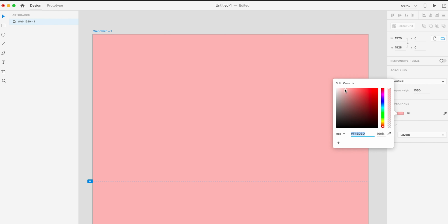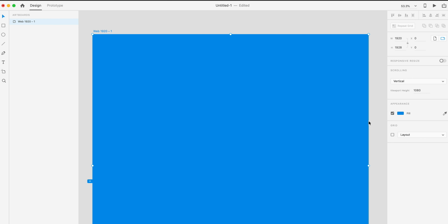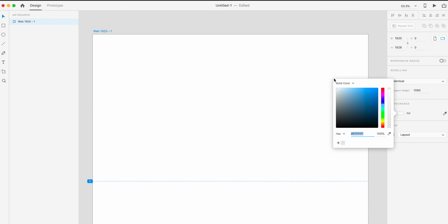So if I select a background color here that I'm going to be using later, right below, I'm going to just click this Save Color Swatch. And there we go, that color swatch is saved. And it will show up in any other color picker throughout Adobe XD. You can also select from existing colors on your artboard by just clicking this Pick Color from Screen. This allows me to select any color I want. Perfect. Now I'm going to switch that back to white.